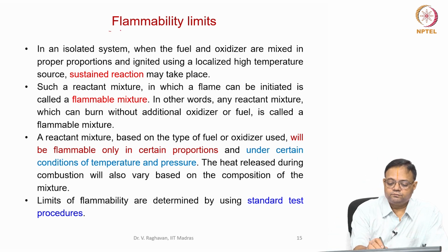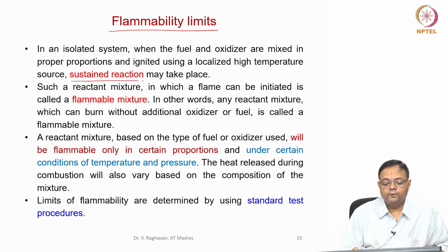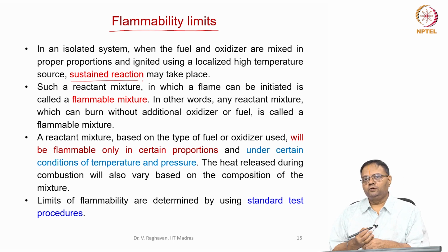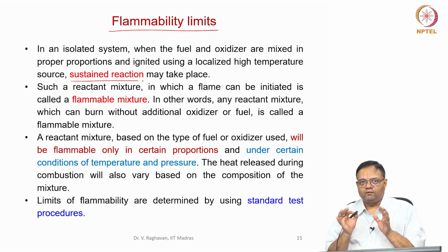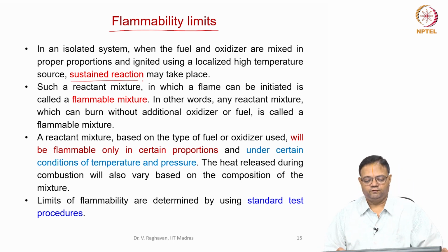Now, flammability limits. Let us take an isolated system when the fuel and oxidizer are mixed in proper proportions and ignited using a localized high temperature, then a sustained reaction may take place. What is an isolated system? I don't allow for any mass transfer. No further fuel or oxidizer can be allowed inside. So, whatever be the mixture which I first send in, that is the composition of the mixture itself.